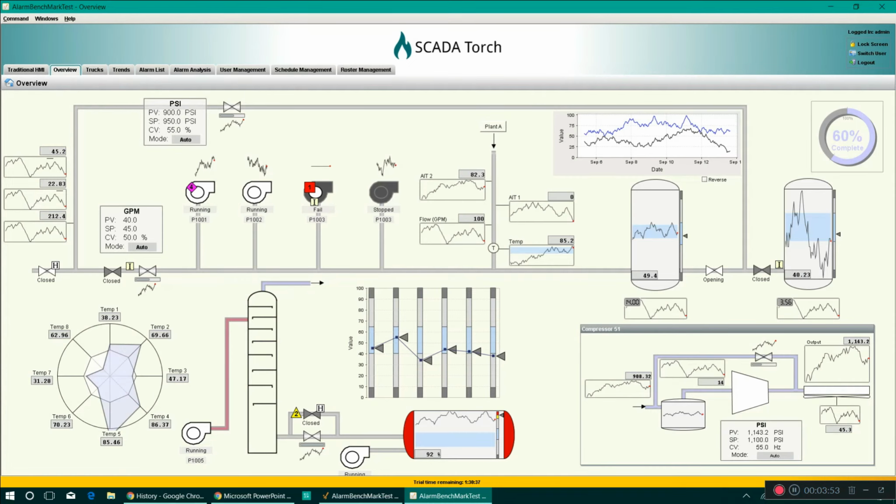If you're still meeting opposition to people wanting to move to a high-performance HMI screen, give your operators just one of these screens. Make a really good level 1 overview screen with the key critical components of their application. Give them the information like I've described here, and let them use it in tandem with their existing SCADA screens. Talk to them after about a week or 2 and see if they want to go back to using their traditional overview screen.